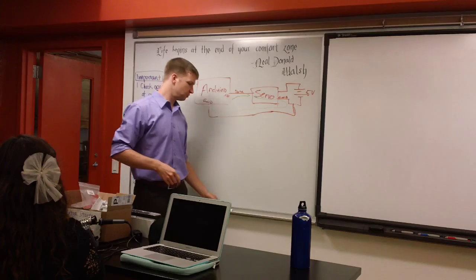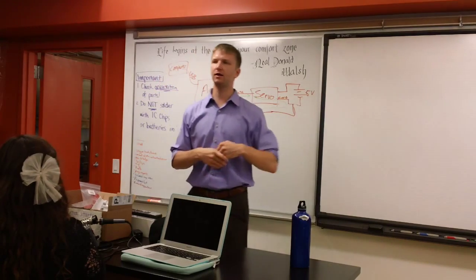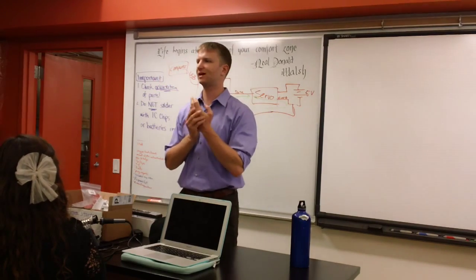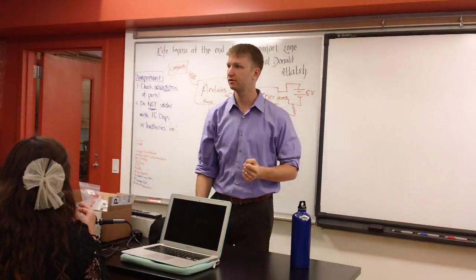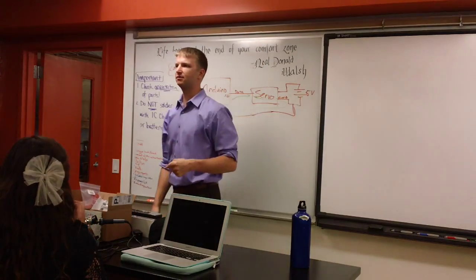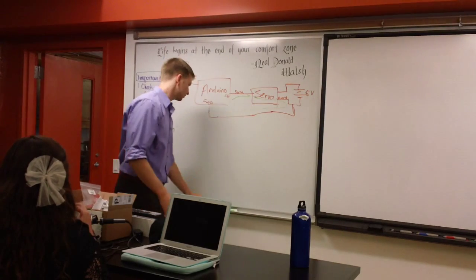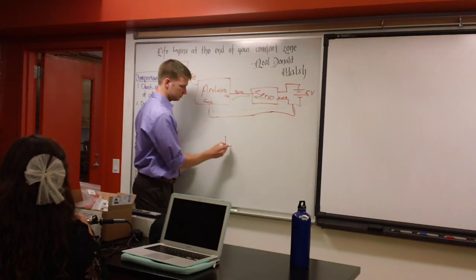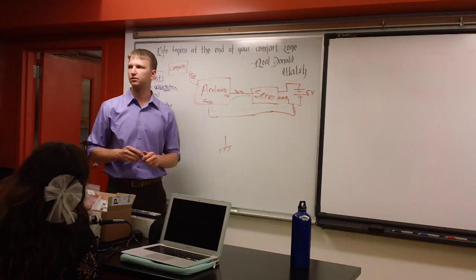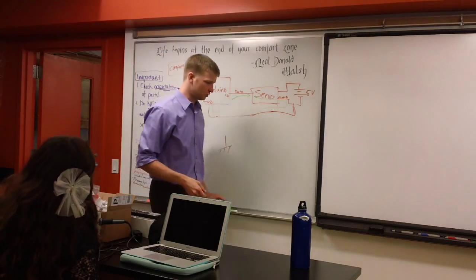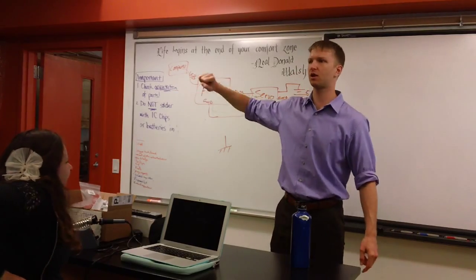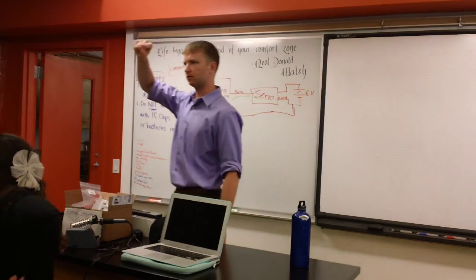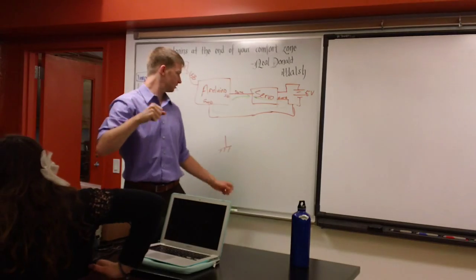But if you want to, you can take an 8-foot section of copper and drive it into the ground, earth, and that is called earth ground. It's got a slightly different symbol. That's earth ground. And so when you have ground coming out of those outlets, that third plug, that round one, that's sometimes there, sometimes not, that's earth ground.